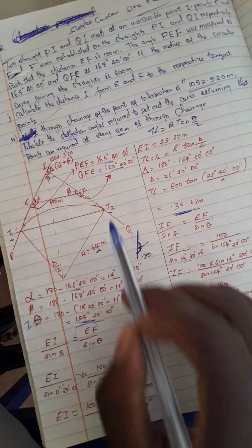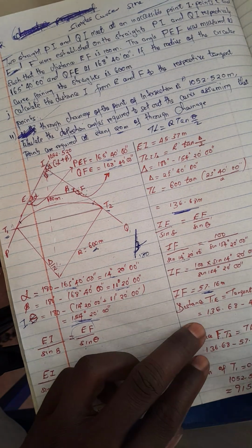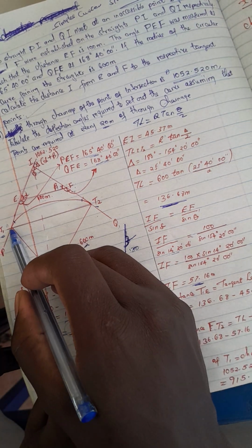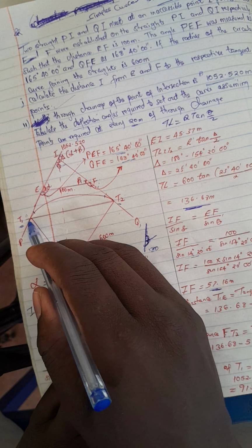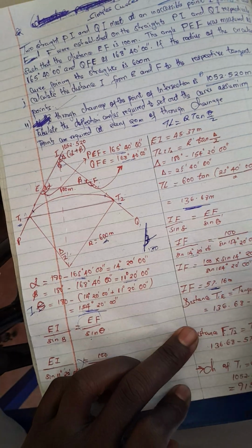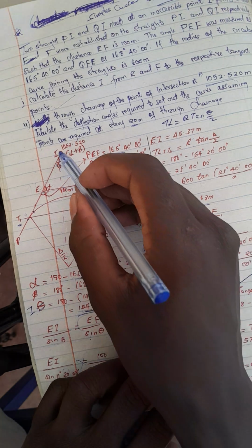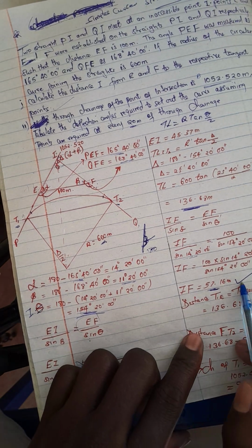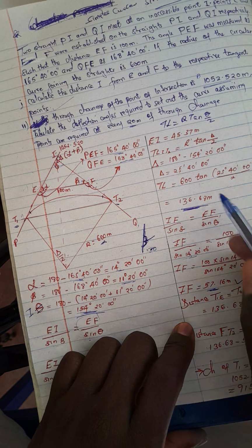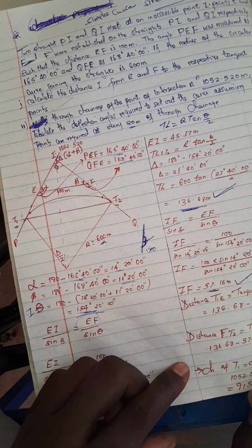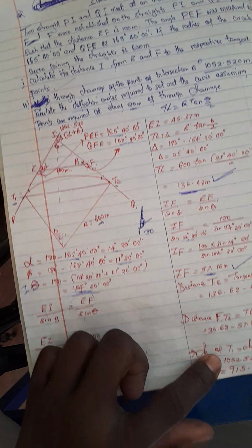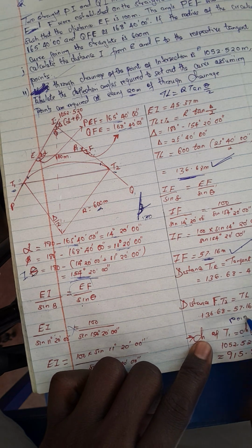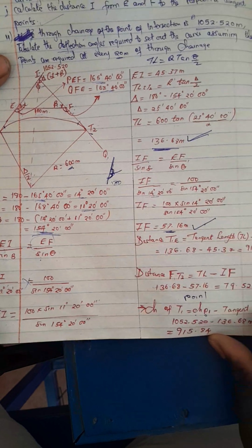For us to get these two chainages, I have the formula. Don't worry. For us to get the first chainage, which is T1, we must first calculate the tangent length, which we have already gotten here, and then we must have the point of intersection. Yes. So the tangent length is here, not here. This here. Now chainage of T1. Chainage of the point of intersection. This is P1, the point of intersection.